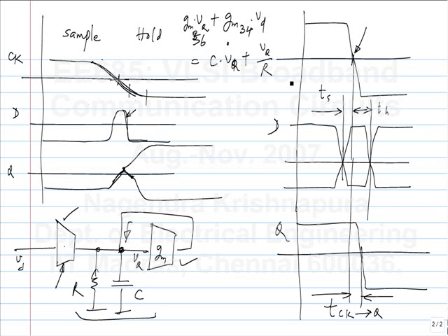Of course, this is valid only when everything is operating in the small signal linear region, but it gives you an idea. Because it depends on Vd, if Vd turned out to be a small positive value and went back to a large negative value, it can flip the initial condition on the regeneration.